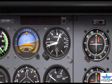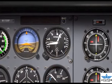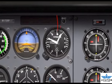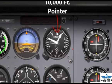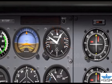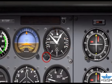The dial of a typical altimeter is graduated with numbers arranged clockwise from 0 to 9. Movement of the aneroid element is transmitted through gears to the three hands that indicate altitude. The shortest hand indicates altitude in tens of thousands of feet, the intermediate hand in thousands of feet, and the longest hand in hundreds of feet. Adjustments for non-standard pressures are accomplished by setting the corrected pressure into a barometric scale located on the face of the altimeter.